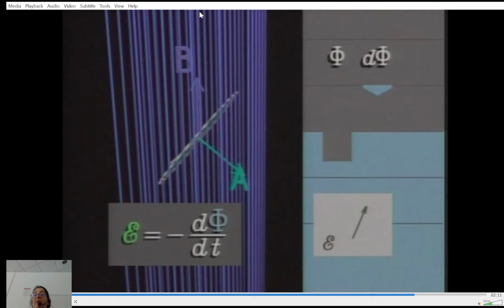So you have a magnetic field that you can produce with an electromagnet, and you have a conductor that you make spin at a constant rate. It's going to rotate 60 times per second. So you're going to get a frequency of 60 hertz. That's the frequency that you get here from the outlet. That's how we produce electricity today. You have a magnetic field here, okay? You're going to rotate that conductor there. So the number of field lines poking through is going to change with time.